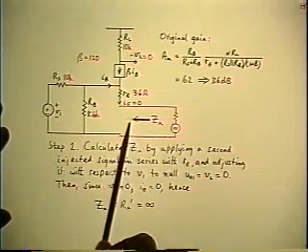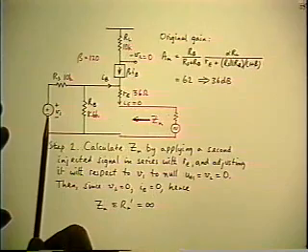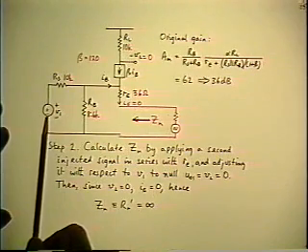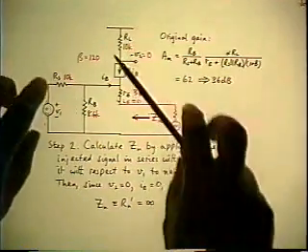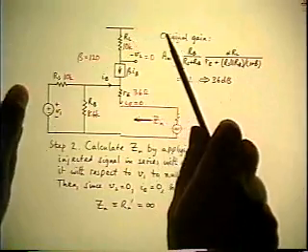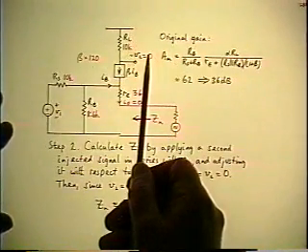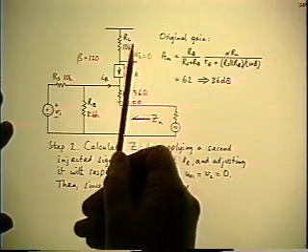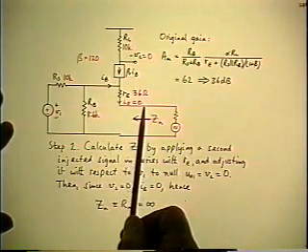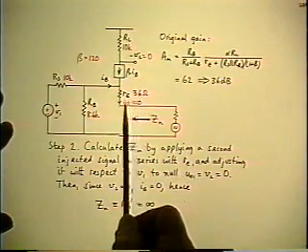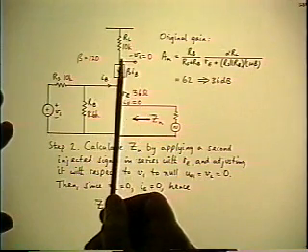Apply a second driving source and restore the original source. So it's double injection. Imagine that you've adjusted the two sources in magnitude and phase until you null the first output. Propagate the null back to the second source and see what happens to the current. So the argument is exactly the same as before.